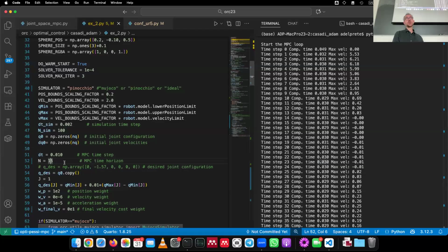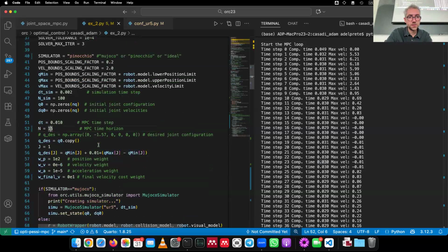And it's instead cubic in the size of the state and the size of the control inputs. So if you make the state twice as big, computation time should grow by a factor of 8. Same for the control inputs. That's because of the sparsity of the problem. The increase with respect to the horizon is only linear. In this case, it was even sublinear.